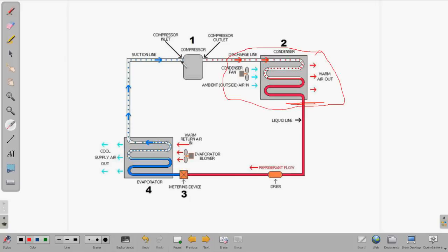Now, a compressor is supposed to and is designed to compress vapor. If liquid starts to go back to the compressor, then we have issues. So again, this system is designed so that as the refrigerant leaves this evaporator coil, it is already superheated, because you may just have a 2 or 3 foot refrigeration line right out the wall to the condensing unit, and there's not enough time to pick up superheat through this refrigeration line. The proper place to measure superheat, if you're doing any troubleshooting, is at the exit point of the evaporator coil.